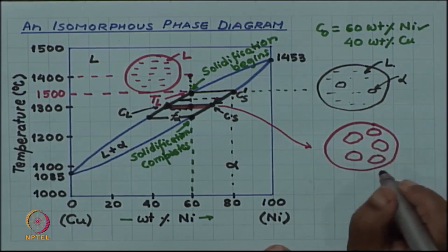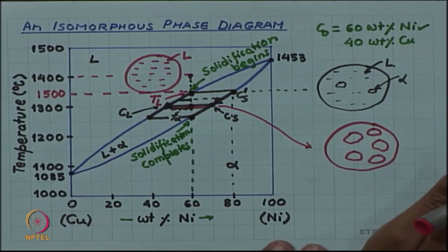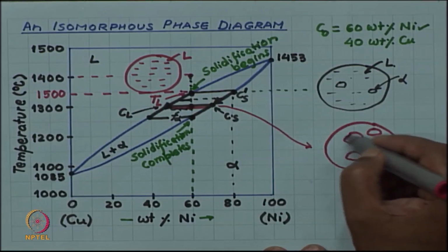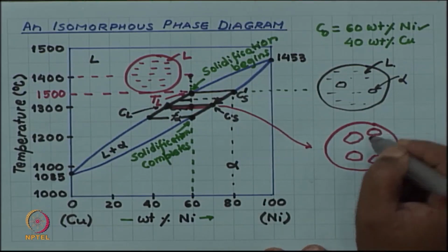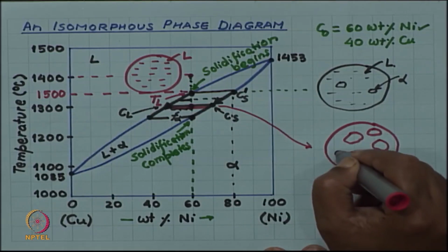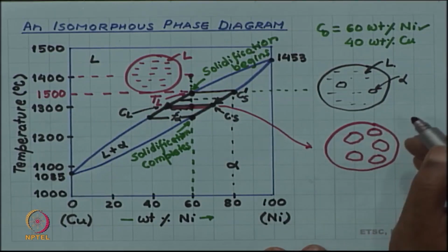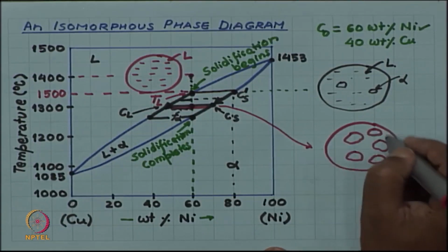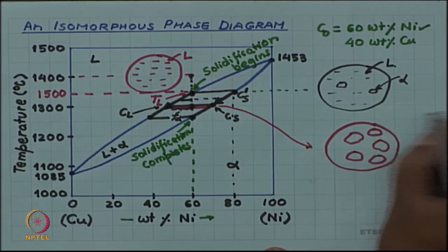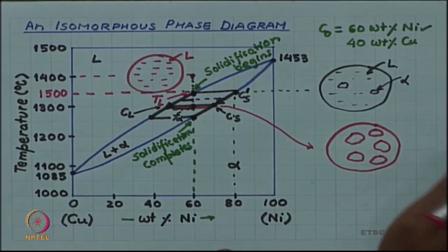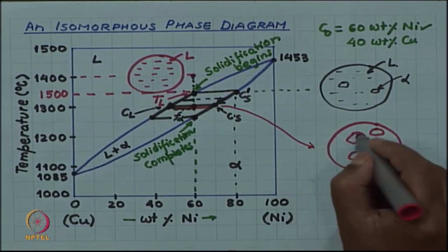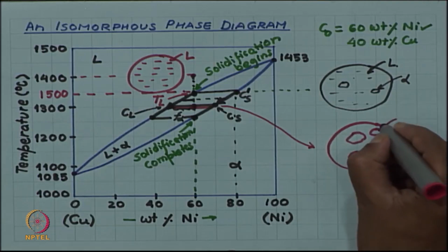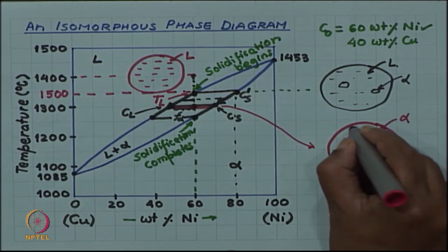I am showing several chunks because this is how the physical process develops, that there are several nucleation sites at which solid begins to form. So, it is not that solid will begin at only one point and that particular point will gradually grow into a single continuous solid mass. Solid begins to form at different locations. This is called nucleation and we will discuss that in detail later, and then those regions gradually develop. So, you have several solid regions developing in the liquid phase.